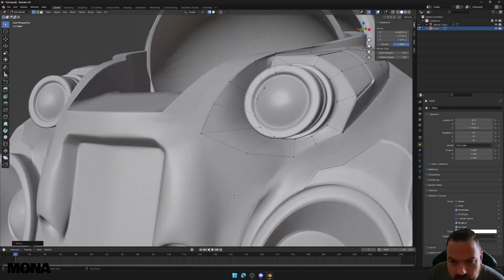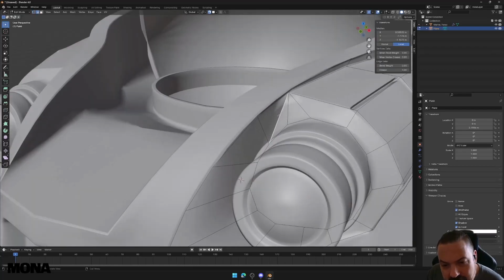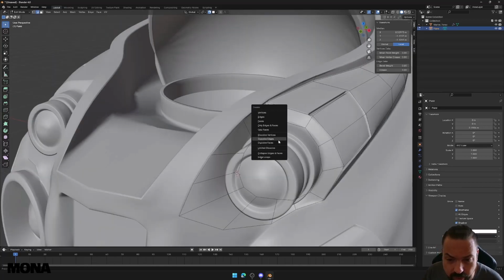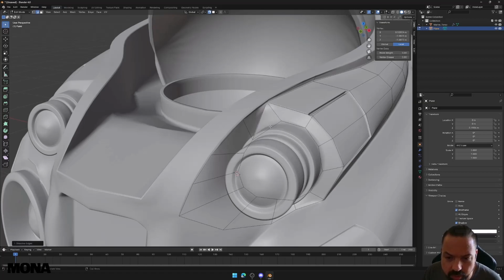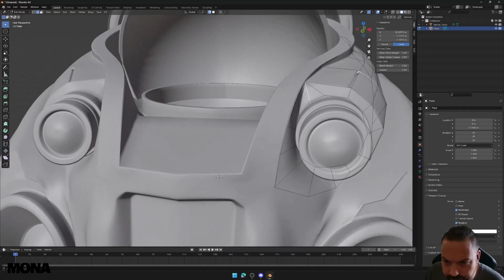Yep. So that's just a removed edge. I'm going to keep that edge there because I want that sharp edge here. Because if I get rid of that, there is a chance that that polygon will actually cut across there. So sometimes, at least, you might want to add triangles to control your polygons a little bit better. I'm going to get rid of that one. Actually, no, I'm not, because I want that there as well.